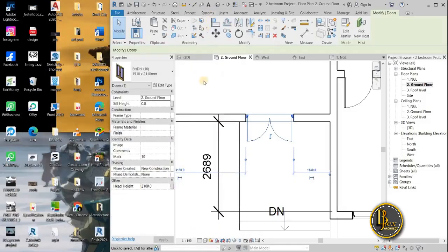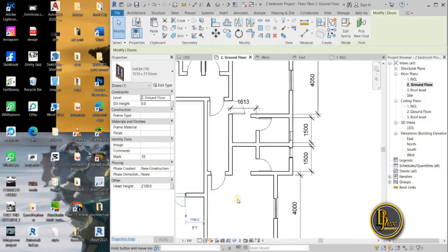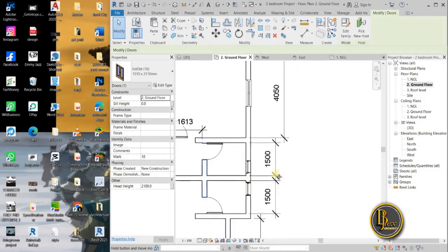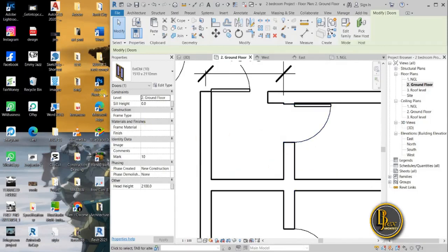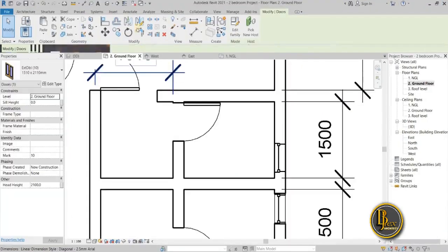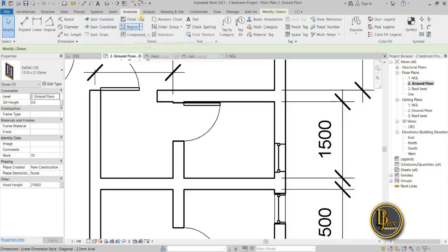Then for this, let's apply our work-in closets. Remember, you don't have to overmodel, you don't have to go and look for a wardrobe or a model from Revit City or anywhere to come and drop here. We are doing a floor plan, so let's just use a detail line to apply our wardrobe here. So when you go to Annotate, you have detail lines.